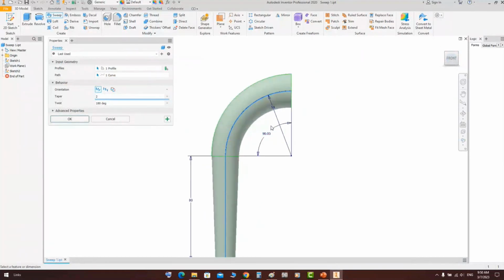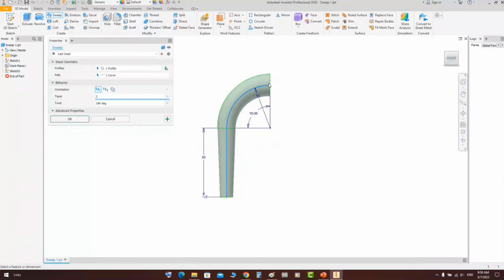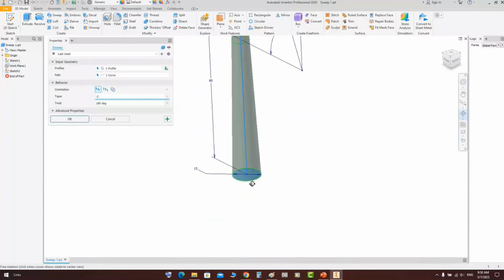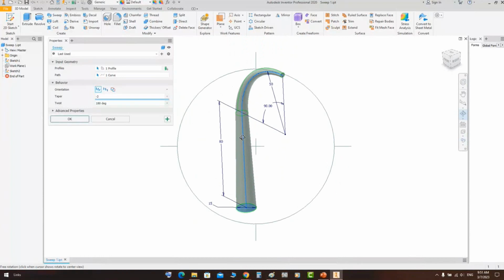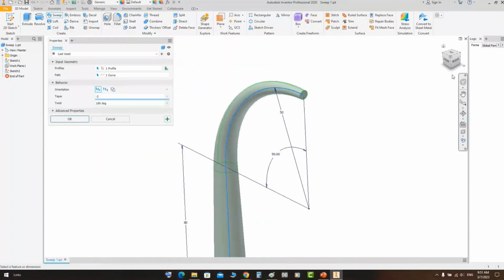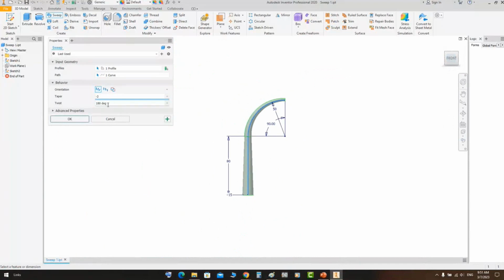So you can figure that the tapered angle increased with 2 degrees up to the end. And if you make it with a negative value, you can get that result. So this cross section will be tapered along that path to get it to the end like that. And you can make it twisted, and we will discuss the twisting option.